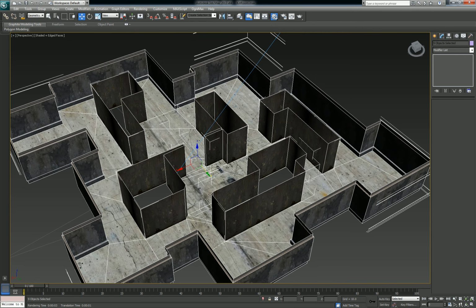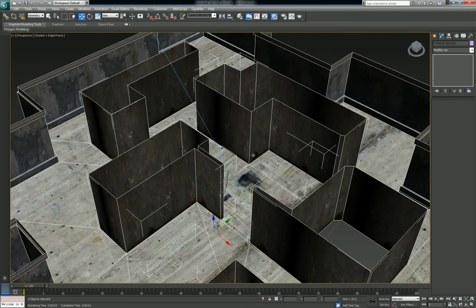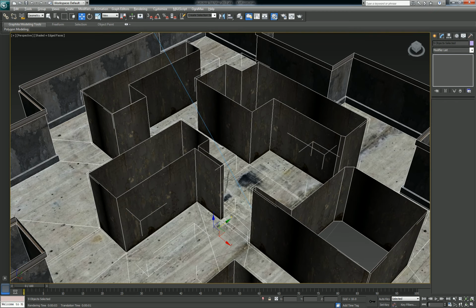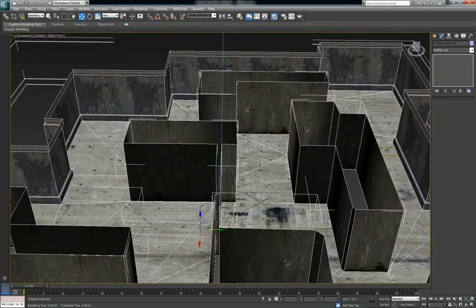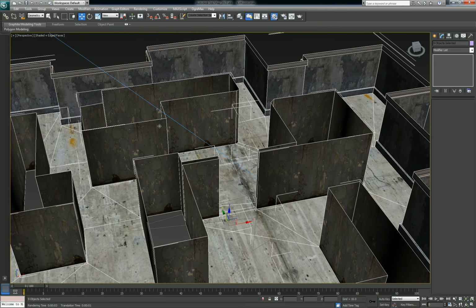Now, something I found out with shader effects is they are probably the most process-hungry performance hogs over and above geometry. So if it comes down to a decision between doing a detail in textures and adding multiple-stage shader effects, I would suggest going with the geometry over the texturing, because the number of draw calls can decrease the performance greater than actually adding more geometry, even if it's twice as much as what we have on a given surface.